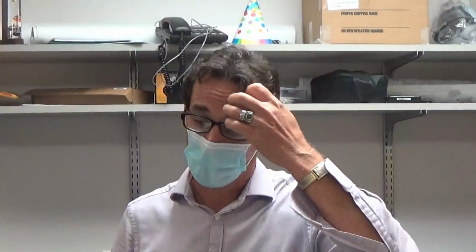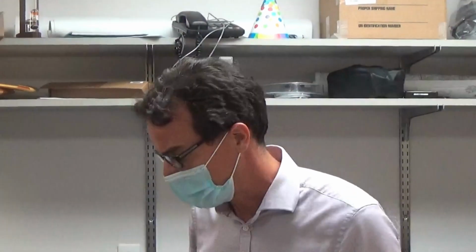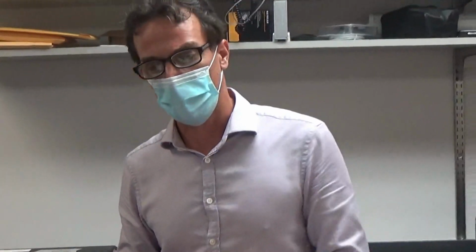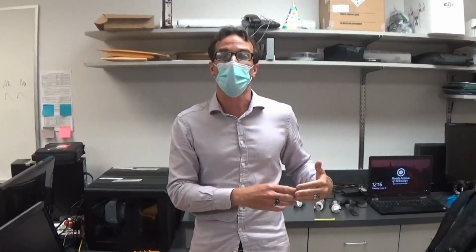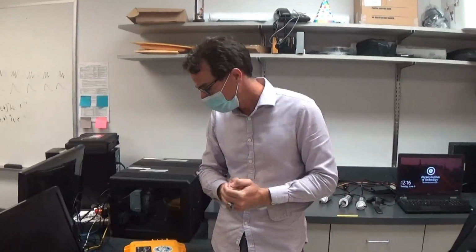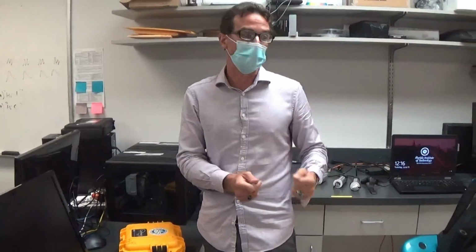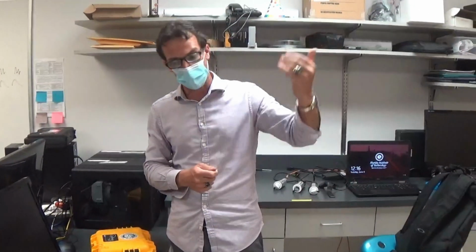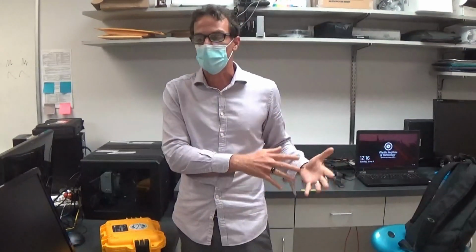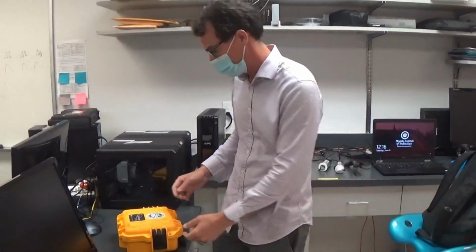sensor head is going to be traveling at whatever the speed of sound in water is, which is a function of the density. So oftentimes when we're running ADCPs that are mounted to the boat looking down and getting current profiles, like maybe we're getting a current profile across an inlet, we'll need to stop and get salinity and temperature readings, a vertical profile of those readings, so then we can post-process the ADCP data and correct for speed of sound.